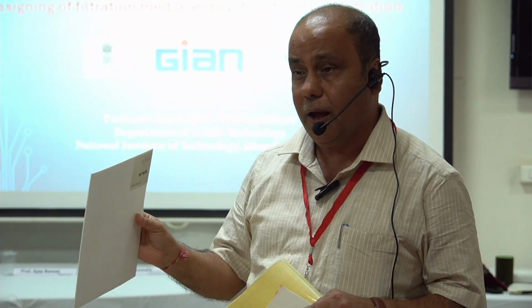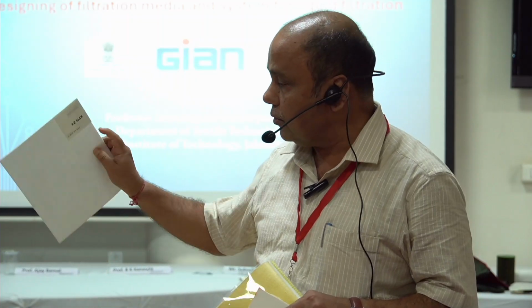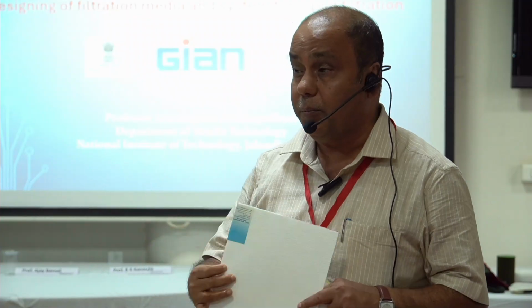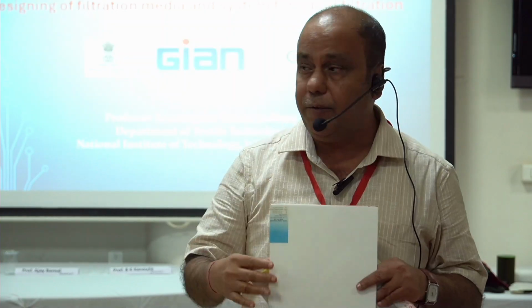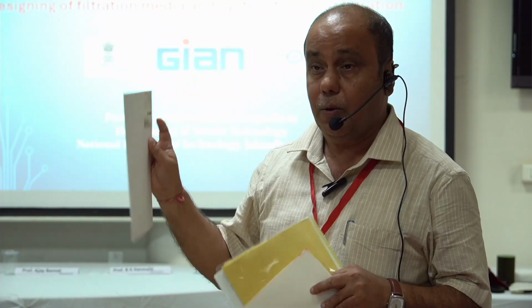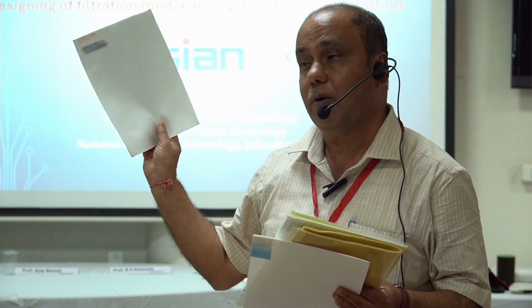Why should it be high? Because one of the problems in non-woven is that if the particles go into a certain depth, removal of the particle becomes difficult. Because of the higher viscosity, the particles tend to move towards a certain depth. If it moves to a certain depth, removal of the particle becomes difficult, whereas removal of the particle will be much easier in the case of woven filter.